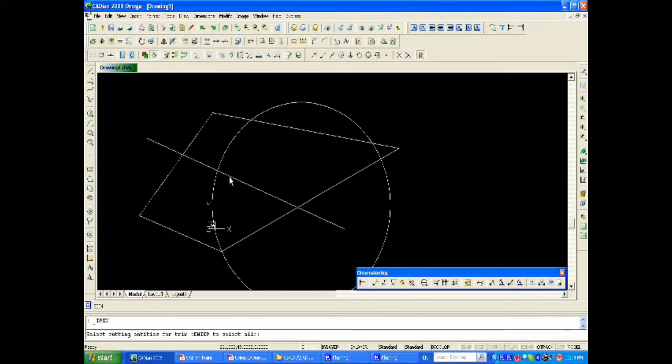Now, I'm going to select this line as my cutting entity. Look what it says: select the cutting entity first. Or enter, you can select all those things. All right, let's just try enter, see what it does. Then it says to me, select the entities to trim. Now, if I pick that, it's going to trim away that entity.